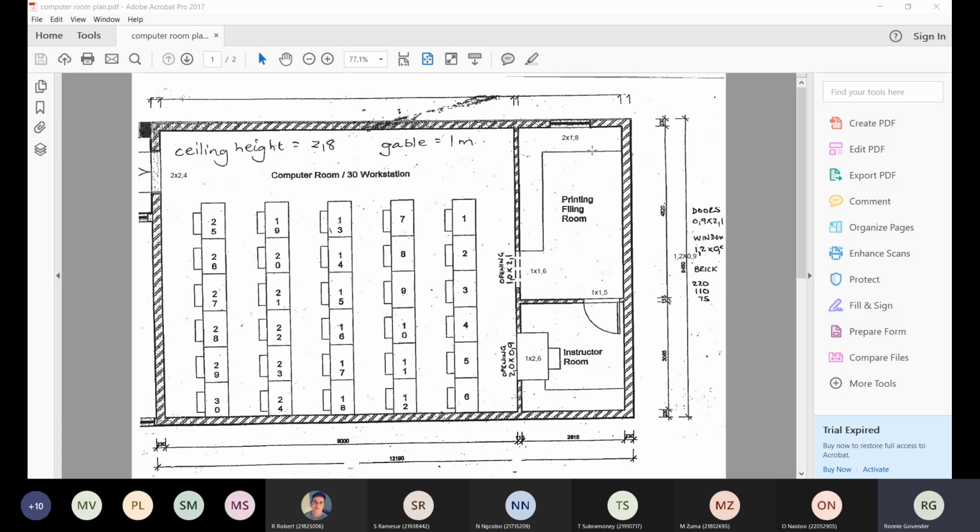Right, if you look at this, first of all, I said this window here is 1.2 meters wide. That's the opening. The opening will be 1.2 meters. So when I put a lintel, I need to overlap it one brick on either side. So that's why I said 230. We just add 300 to it. So 1.2 meters plus 300 plus 300. That's how I get a 1.8 meter lintel. So I'm going to need two of those because they sit butt to butt. 2 by 1.8 meters for there. This opening here is 0.9, 0.9, which gives me a 1.8 meter opening. Plus 300 gives me 2.4 meters. I'm going to need 2 by 2.4 there. You understand? Is that okay now?